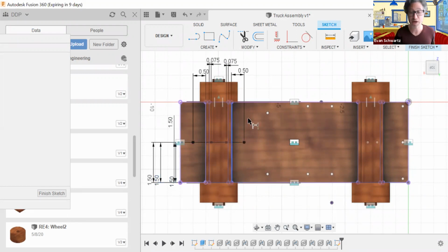Okay, so we're now going to go over to here, and what it tells us is that it is 1/2 inch from here in this side, and let me see here, 1/2 inch, and then 1 3/4 inches from here. So I'm going to dimension this first from here to here, and that's going to be 1.75.